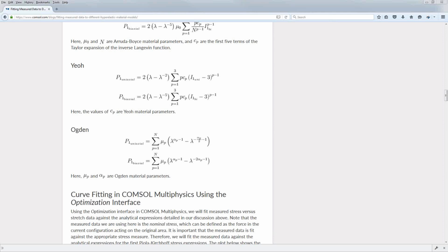You should look into getting the data for other modes of deformation like biaxial or shear or volumetric compression if there is sufficient amount of compression going on or volumetric change happening in your model. And the reason is that when you do uniaxial tests, you have no information whatsoever of the deformation in other directions, second and third. So how the deformation in those directions coupled with the deformation in the direction you're stretching is really unknown.